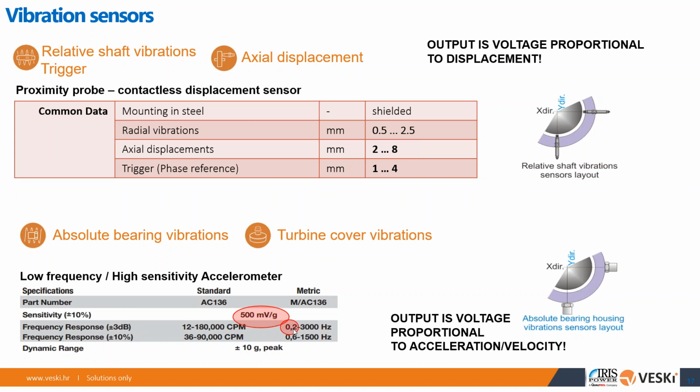The other thing is that it has to have a low cutoff frequency, low enough so you can get a good enough response. Again, I'll just mention one thing. The phase measurements on low frequencies are not as accurate. You don't have time to go into details, but the closer you get to this frequency, the phase distortion gets bigger. But it's still accurate enough to get a decent analysis out of it.